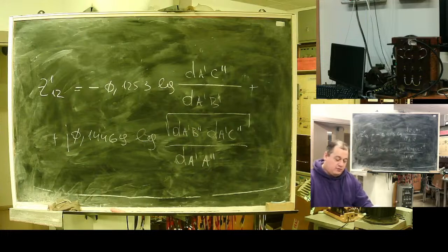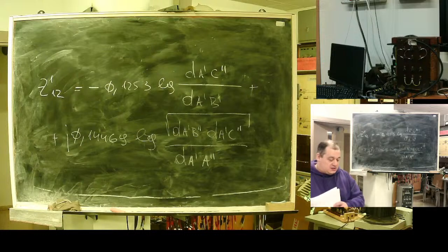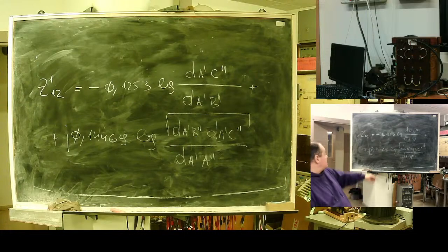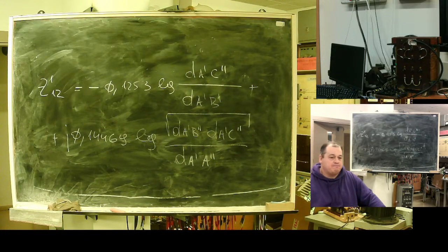If the system were fully symmetric or fully transposed, everything is fine, induced current will be zero. But since you have not an ideal system but a real one, which is non-symmetric, this term will be not zero, and you will get induced current in the disconnected line from the load regime of the neighboring line. Okay, I understand. My time is